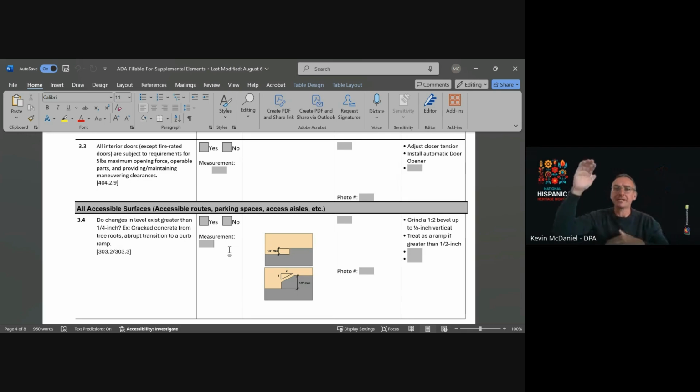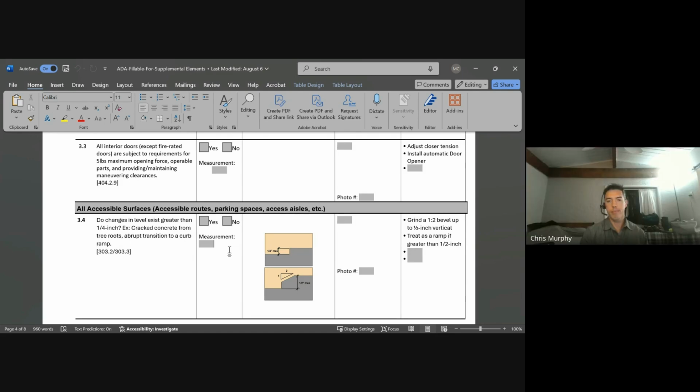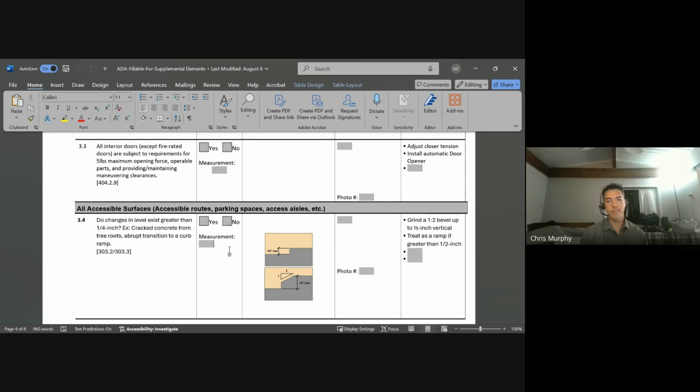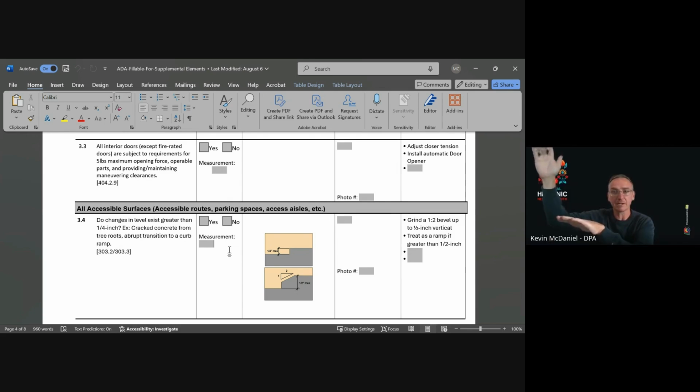I think I understand what she's saying now too. So basically we're talking about an area that is 27 inches from the ground, so about 2 foot 3 inches from the ground up to 80 inches. We don't want protruding objects. You don't want like a block of cement sticking out of the wall. So I think she's thinking about kiddos, so a lot of kids 2 foot, 3 foot tall. Anything below 27 inches can protrude because a white cane would pick it up. So I think she's thinking about students who may be smaller, but actually, yeah, they would still pick it up with the cane.